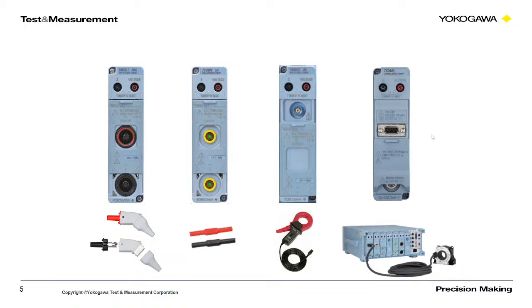And one of the important things we have with the covers is we can't do both the voltage and the actual current signals coming in. So the covers are there to protect you, because with older instruments we know that people try to hook up both, and the modules do not like that. So what you don't want to do, which you can't on the 5000, what Christian is saying is, if you plug in a current here and then to the BNC that's hidden here at the same time, it's no bueno.